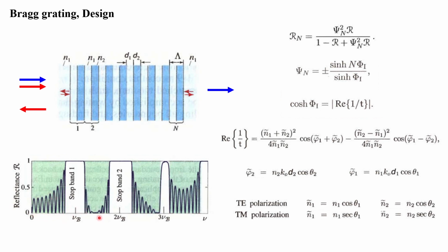As you can see here, this figure is plotted based on the frequency. At different frequencies, we can see we have a bandwidth of reflection. Basically, these bandwidths are the frequencies where we have a perfect reflection, where the Bragg grating is acting like a mirror. Usually people talk about the first bandwidth. However, we should know that Bragg grating has many different bandwidths, and in our design, we can use other bandwidths as well for our desired purposes.